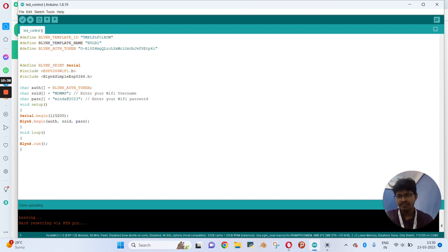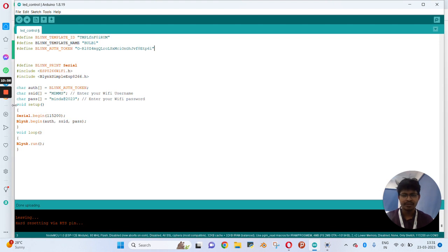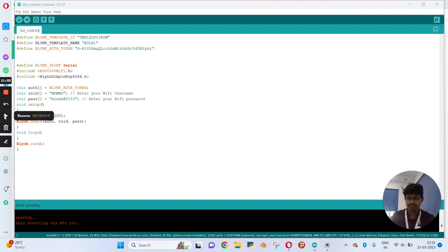And as we have discussed these lines earlier, here we just need to provide SSID and password for our hotspot through which the NodeMCU board will be connected. Rest all things I have explained earlier, so you have to just follow all these exactly. Now we just need to connect our NodeMCU board with your PC.